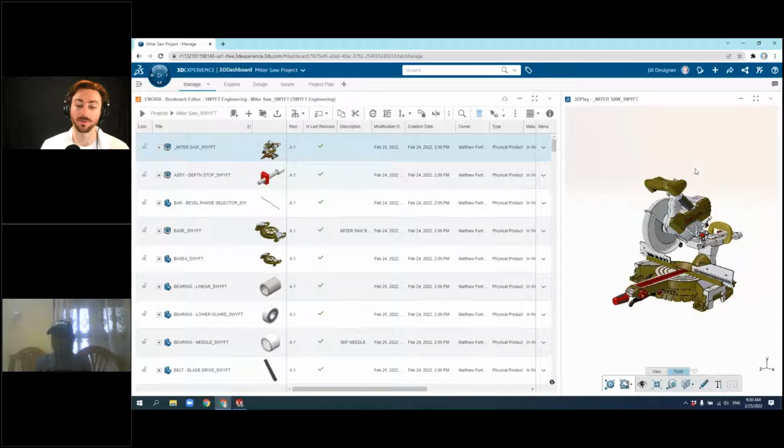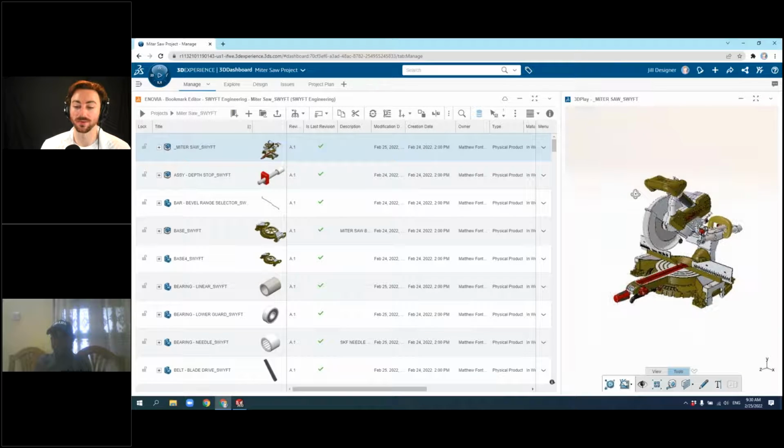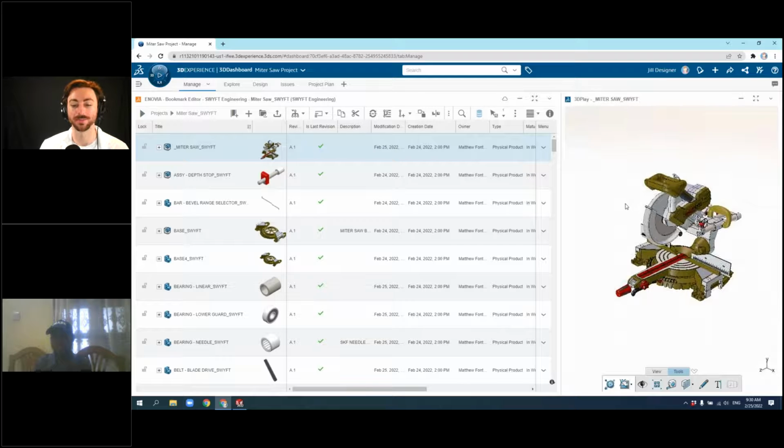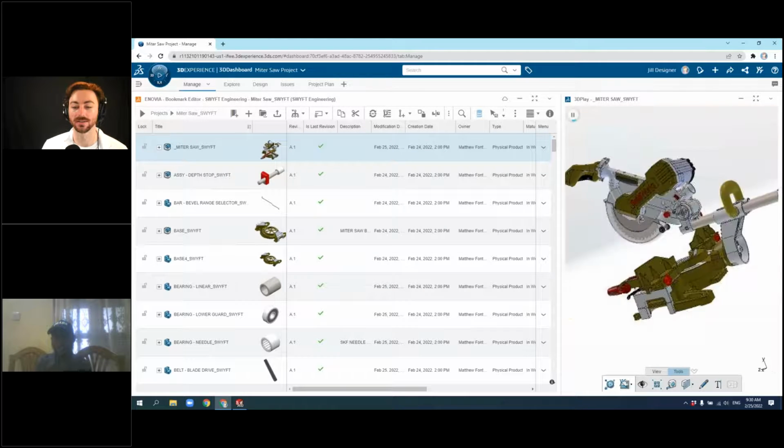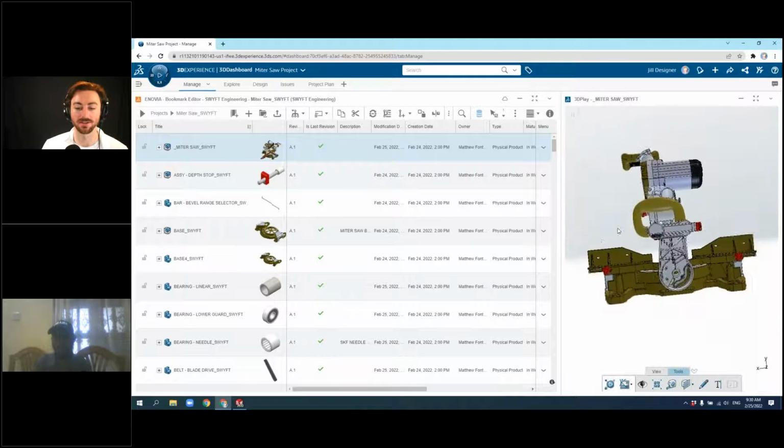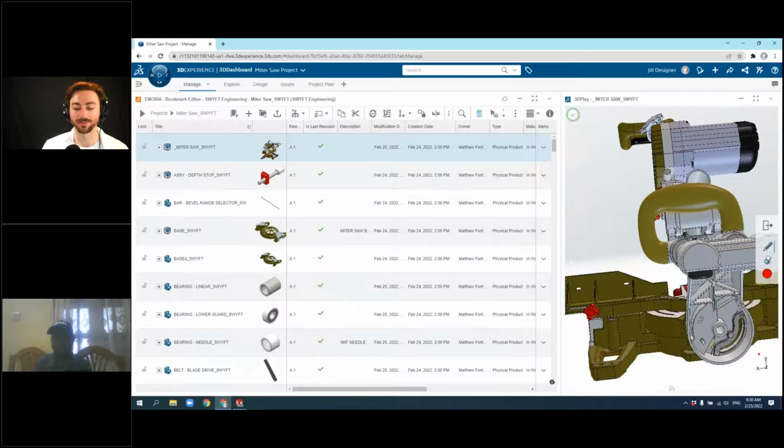SolidWorks users can jump in and view it wherever they are, even if they don't have SolidWorks on them. But two, if you're working with somebody that doesn't use SolidWorks, they can still view what you're doing, the status of it, and provide feedback. There are different viewers on the platform itself, but even with this viewer, you can come in, and I'll apologize now for my messy drawing here, but you can give some markups here. If you have a tablet and pencil, it'd probably be a lot more efficient. You can give text callouts.